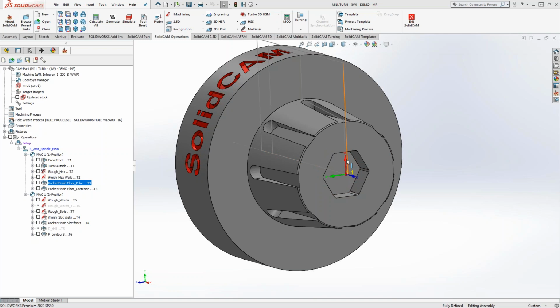And it's exactly like Kevin said. There are some machines out there that, even though they have live tooling, even though they are probably a full functional mill turn, they don't have any Y movement at all, or maybe it's so limited that if we were to do this corner right here of the hex, it doesn't have that much space for whatever reason. Now this is kind of a weak example, but you can imagine something that's a larger diameter can't really move all the way over here.